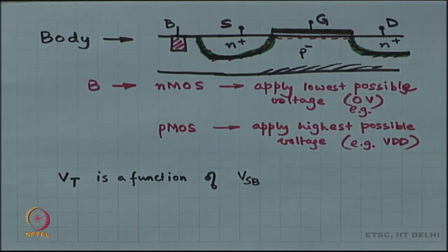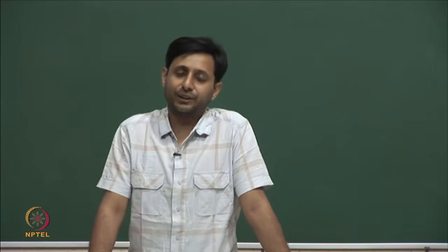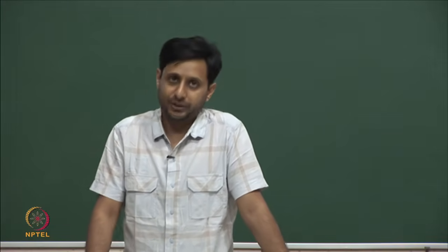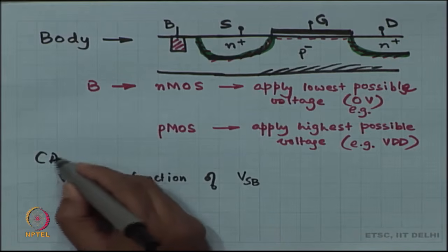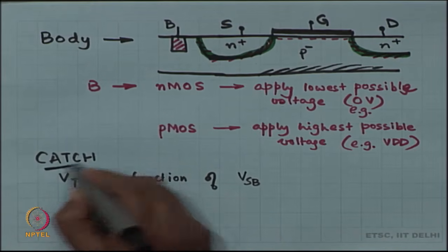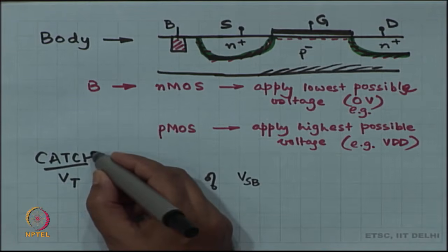Okay. So, if the source is changing, right, then the source to body voltage is going to be changing, and that means that Vt of the device is going to be changing. So, this is the catch. All right, and this is something that you have to be aware of.